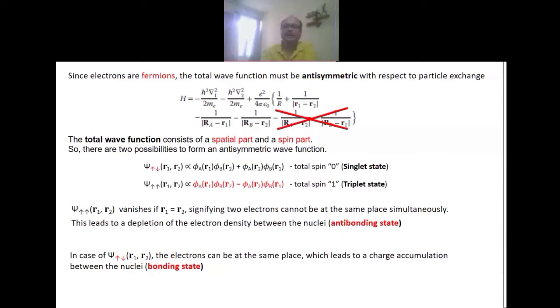These are discrete levels that can be formed within the boundary, in the dots. If you think of the bulk, you have certain levels; generally the gray color shows the bulk levels. But in the case of reducing dimension, your levels will now be quantized. They are separated out, which means the quantum dot can absorb different amounts of energy. Utilizing this effect, people are making LEDs.